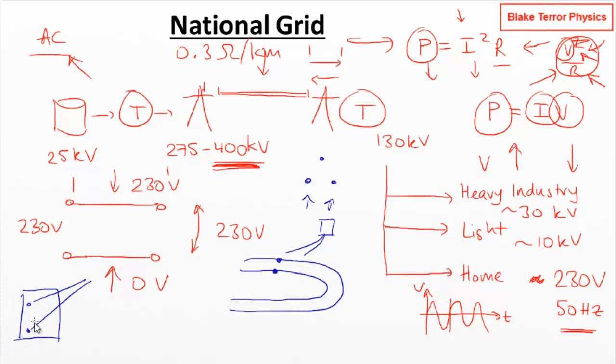And then we can manage a lot of what's going on, the fuses and such, all on the fuse board. This means you've got more cable going out and back all the time, because every time you've got a socket in the wall, you've got cable going out and back. We don't have that with a ring main, because we're just running one long wire all the way round. So if you want to hook up another plug socket, well, you just stick it in. The wires are just there, ready to go, providing it's adjacent to the two rings. So it uses less copper wire from that point of view.